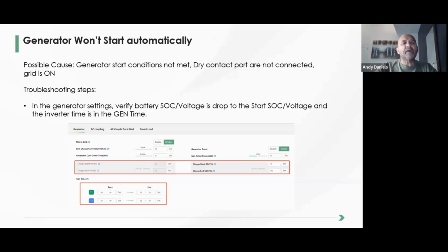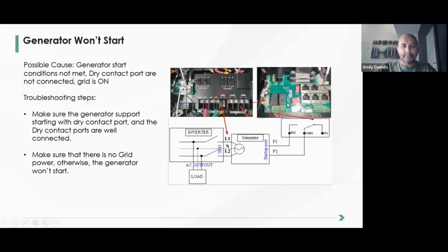That's the one thing. And if you have a very old generator, a nice trick to do is to put another load on the generator, a smaller load, so that the voltage regulator can bring the voltage and the current within frequency within parameters. Okay.